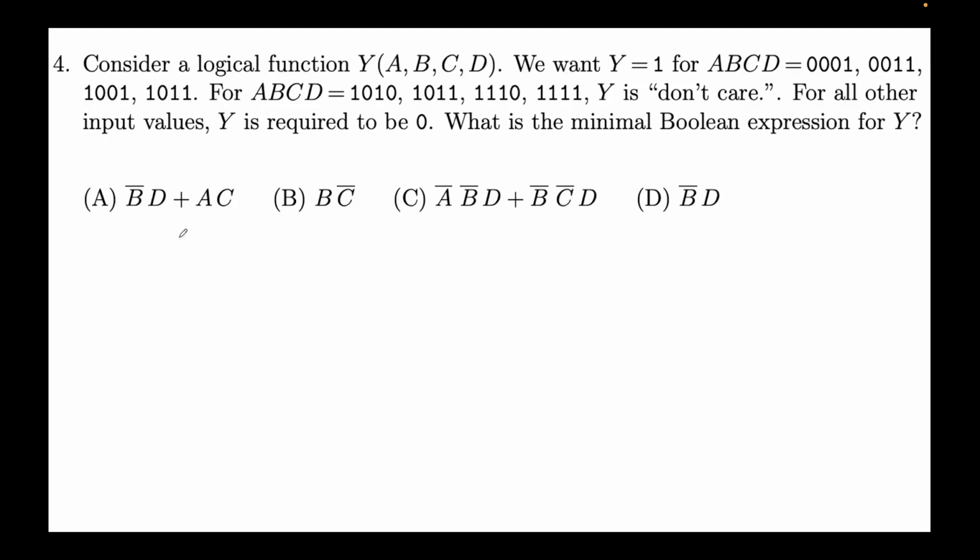So till now we were solving our problems of digital electronics using 2 approaches. First was the truth tables, which we used in the first problem, and the second and third problems we solved using Boolean algebra, where we saw some laws, like f plus g h equal to f plus g and f plus h, and some DeMorgan's laws. Those are laws of Boolean algebra. Now we will move to the third approach of digital electronics, where we solve the problems using something called Karnaugh maps, also known as K maps.